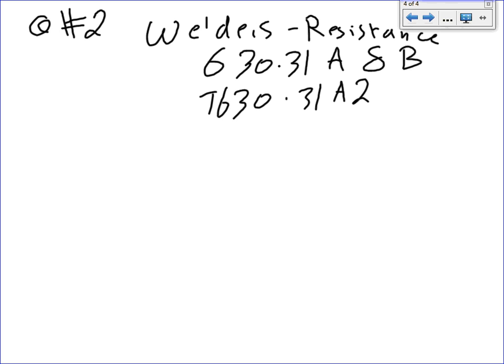You take the full load amp, multiply by the multiplier based on the cycle, and then the largest one is 100%. If you read B, guys, it says the conductor for two or more welders shall not be less than the sum of the value of the largest welder plus everything else at 60%. So you take the largest at 100% plus everything else at 60%.